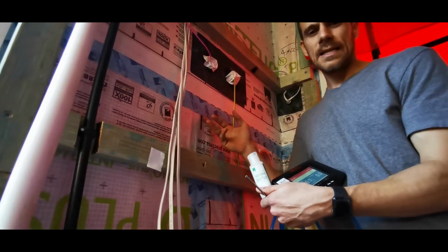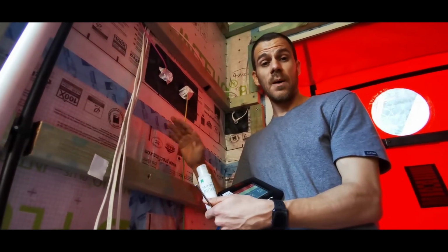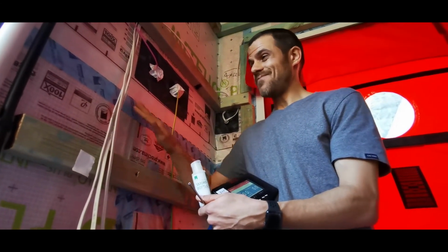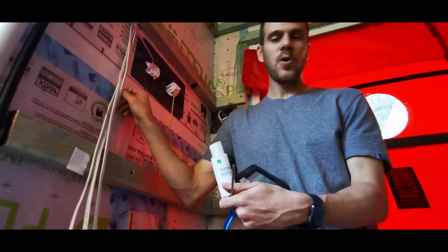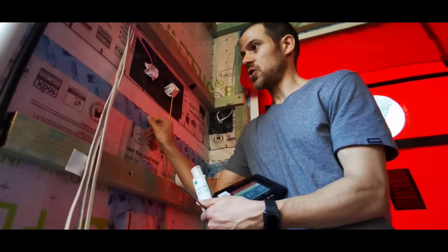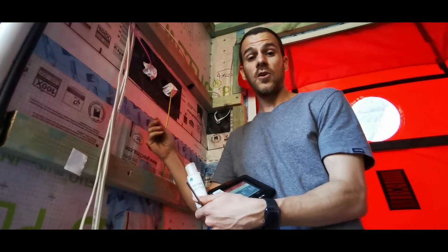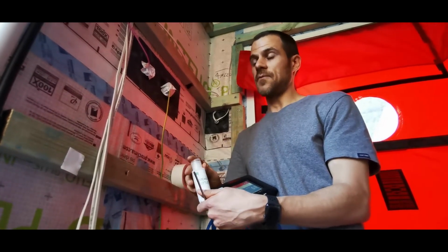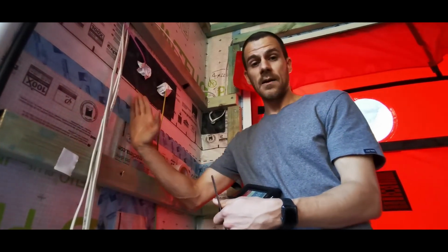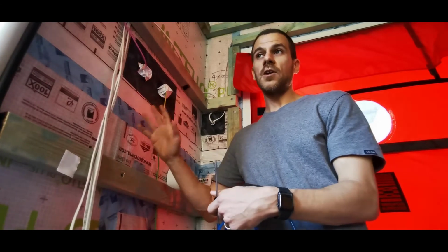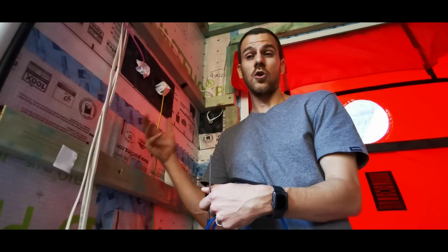So what causes leaks like this? Why is this not sticking to the membrane that's being used for the air barrier? It's because in this case this is a pressure sensitive adhesive. So this product needs a pressure tool to press the adhesive into the surface of the membrane to create a good lasting connection. Lots of different products have different needs. They're roller applied products. Others use blades to press them in. But whatever it is, you need to make sure you're following the manufacturer's directions for creating a good, durable seal.